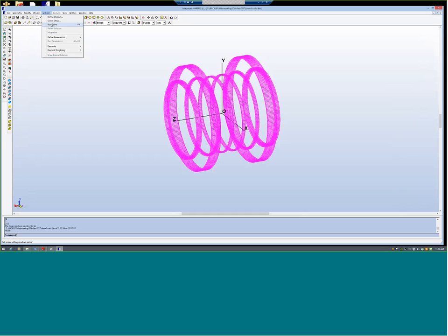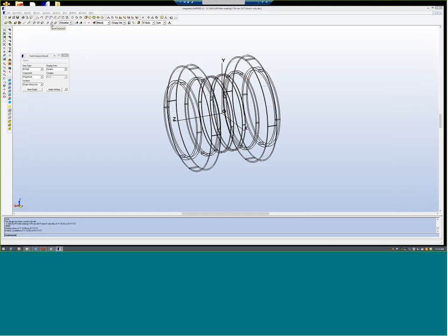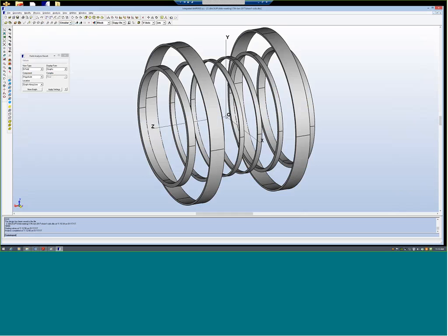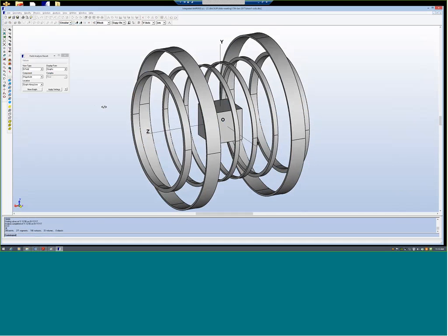Run solver. Now you see here, because these coils are a source of current which produces the magnetic field, and all the currents are well known, there is nothing to solve. That's why the solution comes instantly. So now I want to see what the fields are in the center, in a cubic foot. Let me create a cube here, center 0, 0, 0, 30 centimeters is the side. Let's take this.